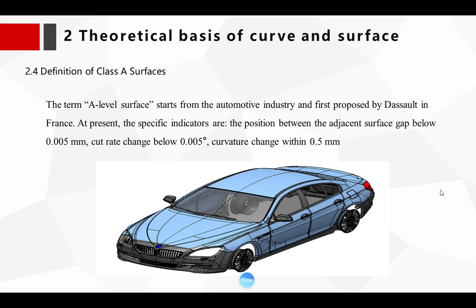The position gap between adjacent surfaces is below 0.005 millimeter, the tangent change is below 0.0052, and the curvature change is within 0.5 millimeter.